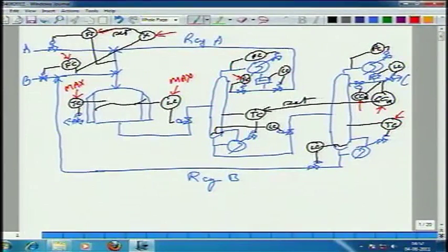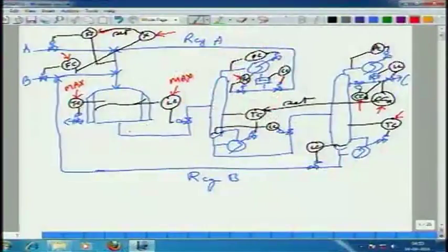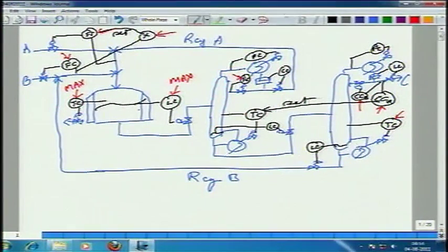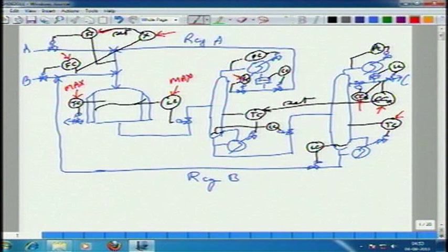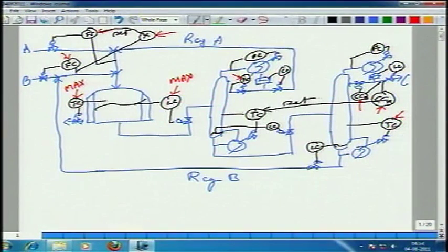What does this flow controller do? The set point of the total B flow controller will be used to increase or decrease throughput. If I look at the reactor, and let us say I increase the total B flow set point by 20 or 30%, how does the production inside the reactor increase, or why does it increase? It is very important to understand this. Is the question clear? I increase the total B set point and I get more production of C. My question is why? What happens inside the reactor to produce more C?